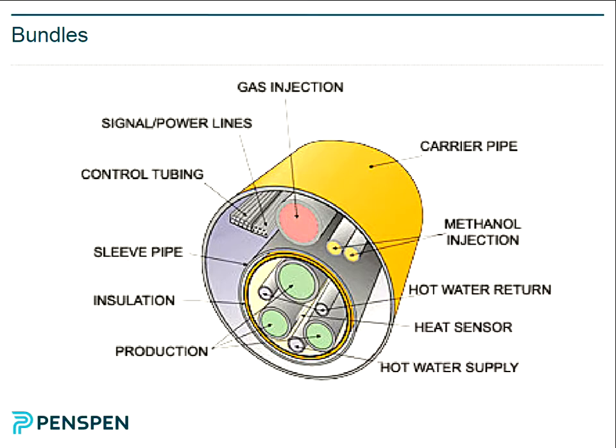You use it in a situation where you feel you can manage the corrosion. And often you'll find the pipelines inside bundles are corrosion-resistant alloys. Some of the ones I've worked on have been using stainless steel for the inner lines, so again, very expensive.